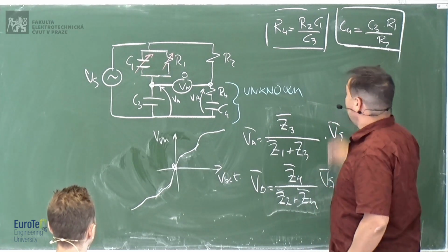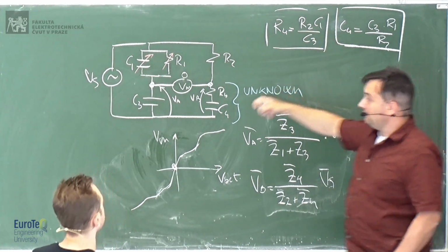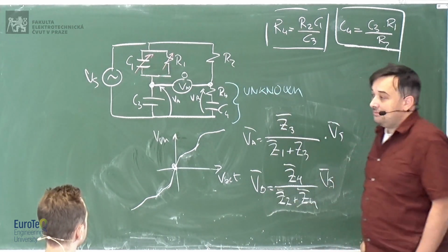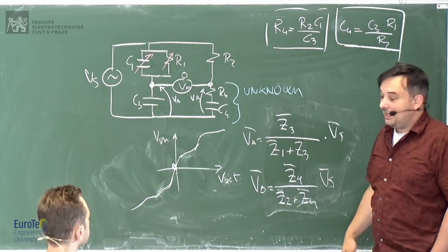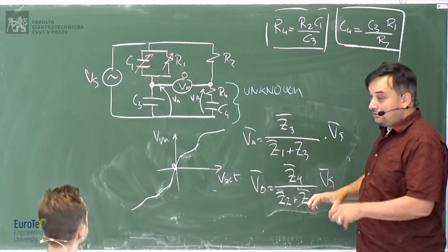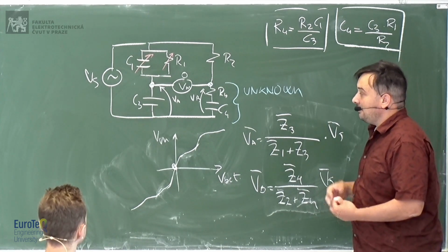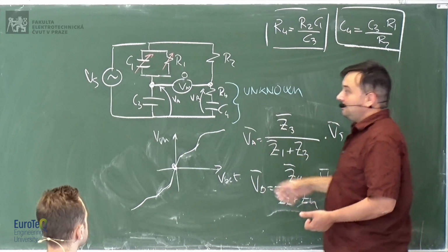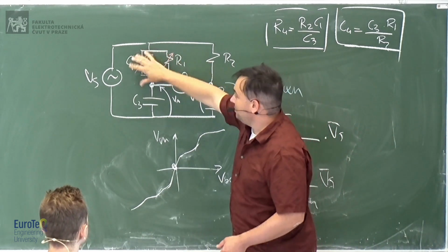So if you watch here, it depends only on the components of the bridge. But to some extent, you can have these components very good. You can have components which have very high precision. You calibrate them, and you put them in the circuit. You can also have precisely tunable resistors and capacitors, and you're fine. So there's really not a big deal in creating this circuit. The point is that you cannot do something very fast, because every time you change the impedance that you want to measure, you have to change these things every time.